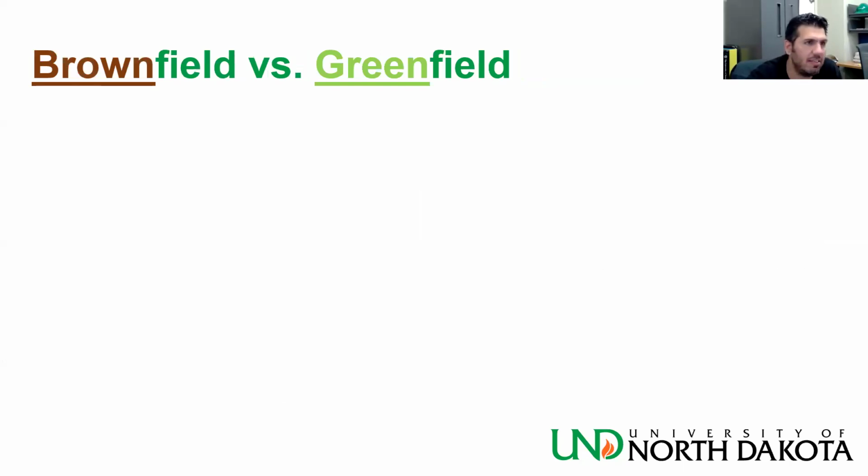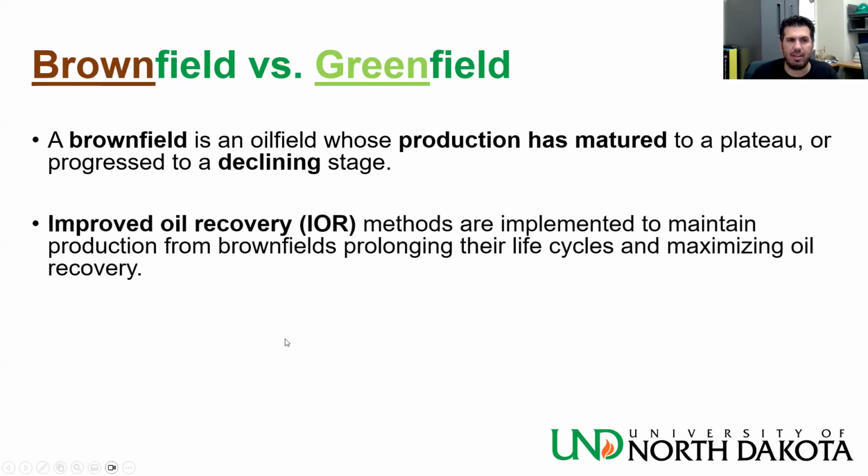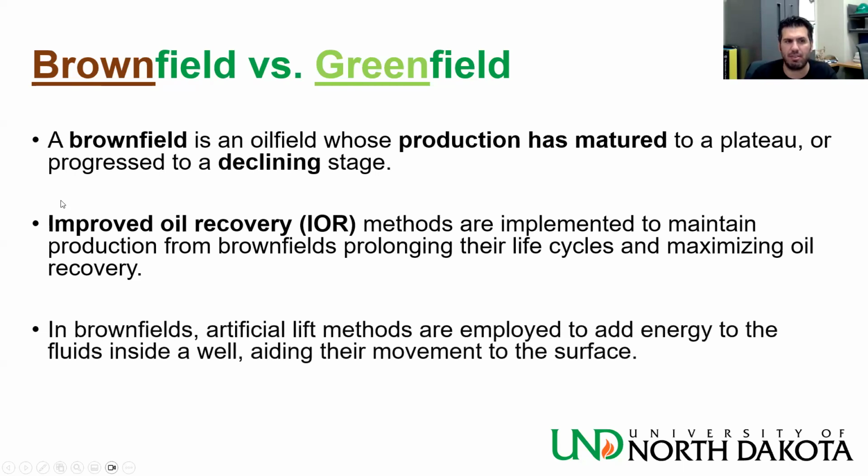Now we have brownfields and greenfields. What's the difference between the two? A brownfield is an oil field whose production has matured to a plateau or progressed to a declining stage. Improved oil recovery methods, including artificial lift, are implemented to maintain production from brownfields, prolonging their life cycles and maximizing oil recovery. Brownfields is where you will see artificial lift methods being employed to add energy to the fluids inside the well, aiding their